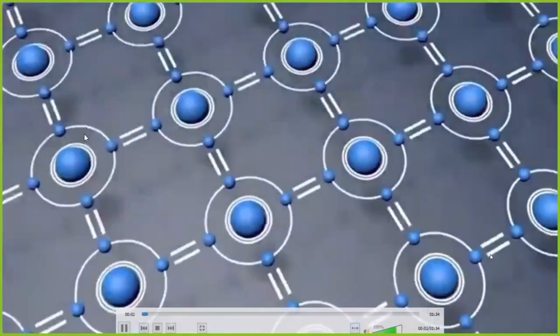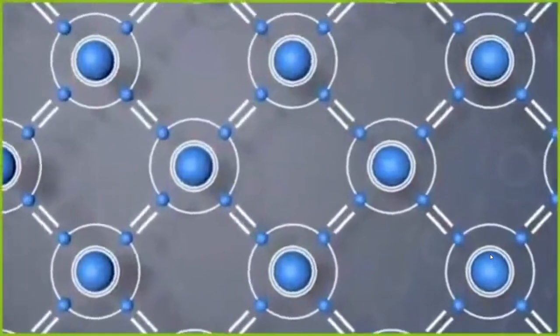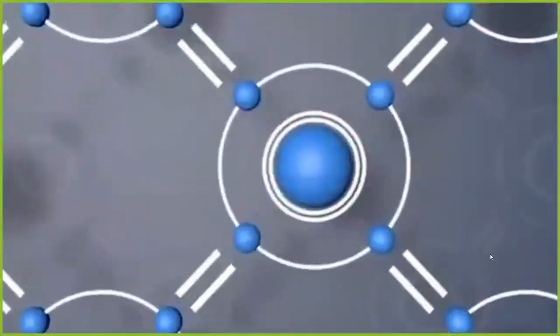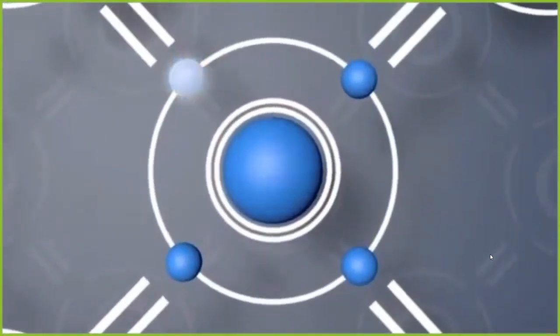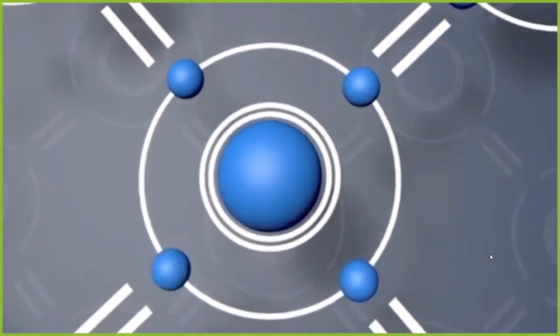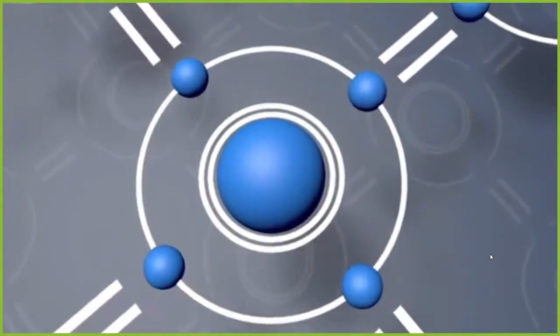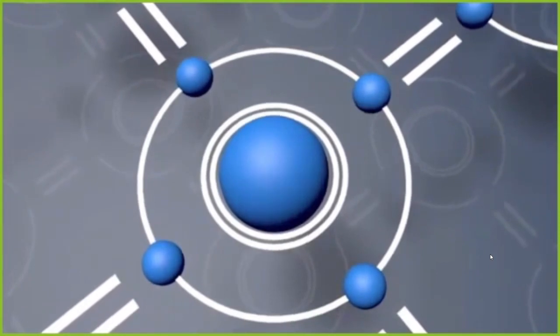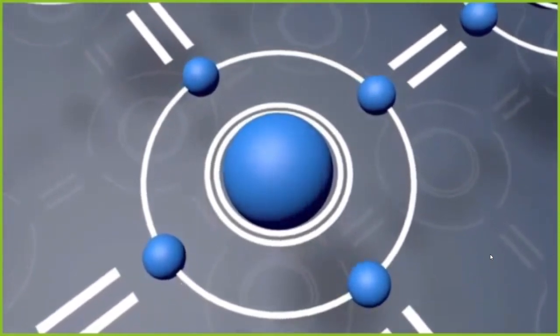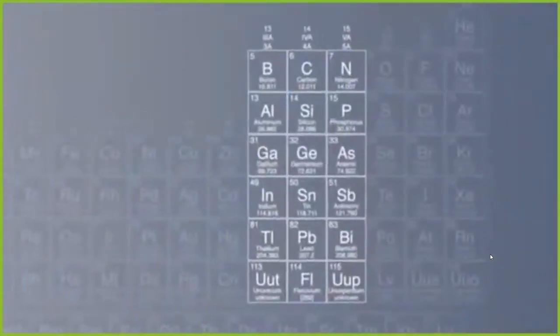Silicon is a semiconductor. This means it can conduct electricity and also act as an insulator. Its atomic structure looks like this. Every silicon atom has 4 outer electrons. There are no free charge carriers. As a result, the pure monocrystalline silicon is non-conductive at room temperature. To allow it to become conductive, small quantities of specific atoms are added as impurities to the wafer. These impurity atoms must have a number of outer electrons that is either one more or one less than that